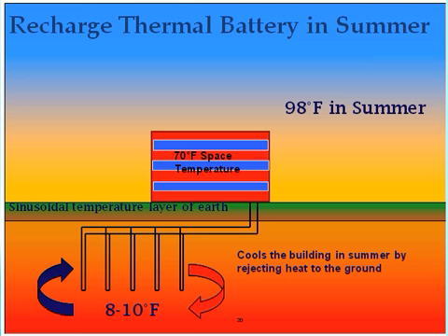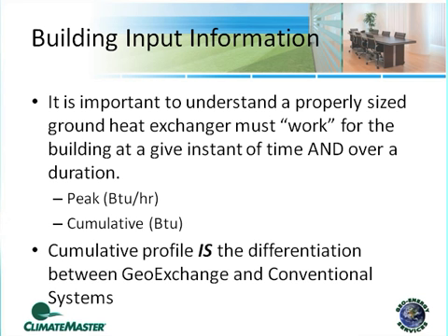Now, depending on where you're at, and on what type of building it is and the application, this thermal battery is going to recharge and discharge itself over time, and there may be an imbalance. Historically, in the south you're going to have cooling-dominated buildings. In the north, you're probably going to be balanced, or slightly heating-dominated, especially when you factor in ventilation. So you have to understand how imbalanced we are, how far out of whack we are. But we can still account for that correctly in the borefield ground heat exchanger design itself. It's an important concept to understand: this is a thermal battery that's recharging and discharging.